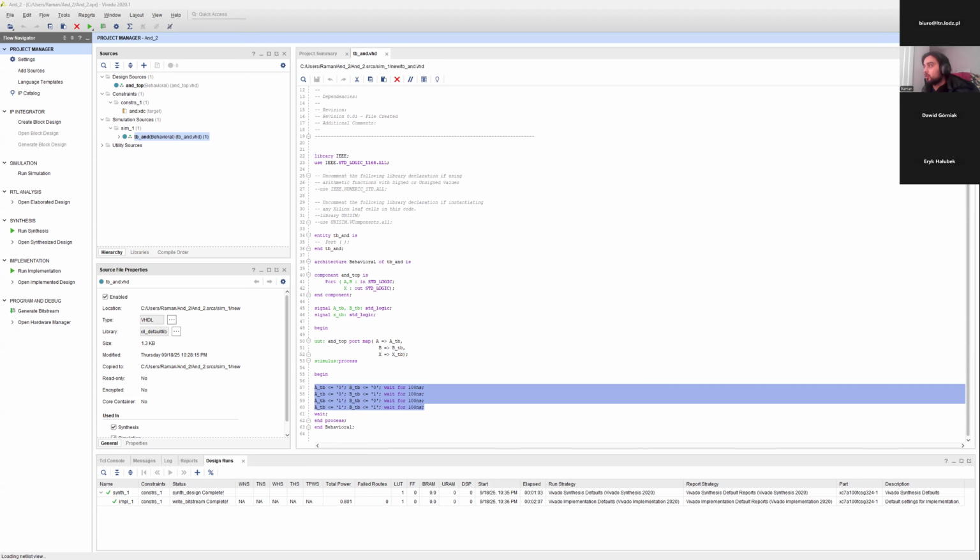So when you open the synthesized design, it'll show you a circuit of your logic, and these are our inputs, A and B, and that's where our code is being processed, right? That's the lookup table where you can see, if you see the truth table, this is the AND gate truth table, right? So this is one of the ways you can verify your results.